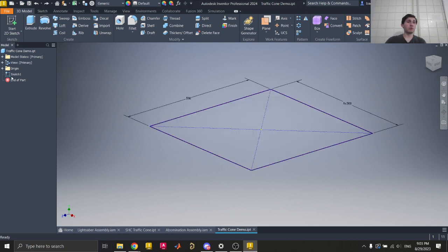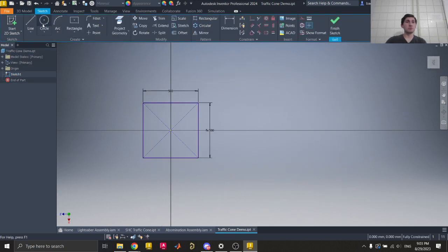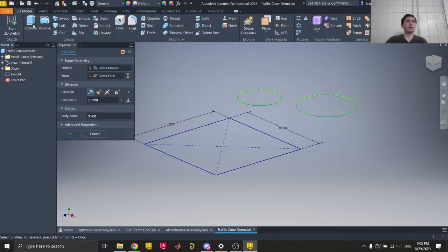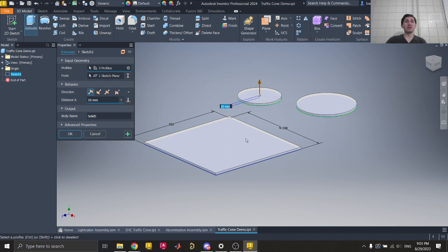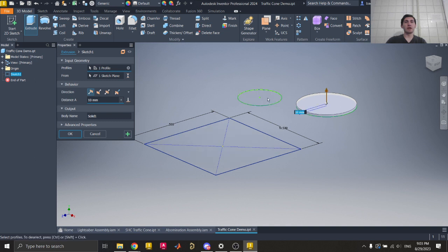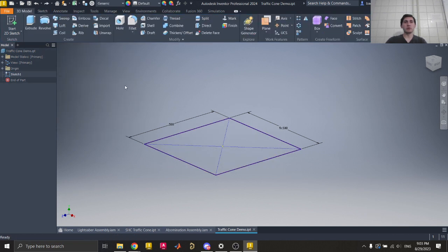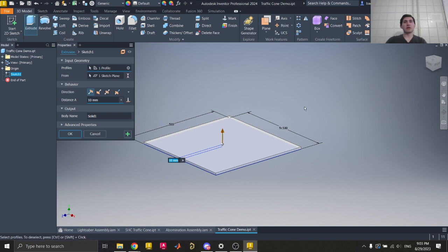I'm going to do one thing really quick. You do not have to do what I'm doing. I'm just doing something for a quick example, making two other regions. If I were to make an extrusion, here it's asking me to select some profile. You can see it's highlighting over a certain square or a circle if I want, and I can click and choose whichever things I want. If I want to deselect something, I can just hold the shift button, and I can either click or unclick certain things. So I'm going to undo those and go back to extrude. So that's the profiles area.